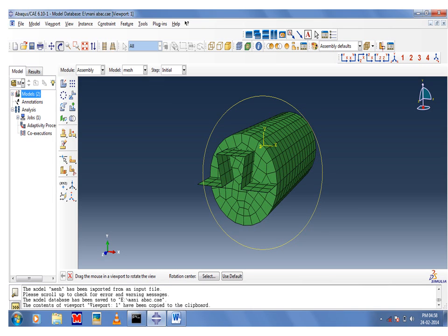The top portion is pulled up from the tuning fork like shape that has been welded on the CF sheet top portion. The bottom portion is pulled down by using a tuning fork like shape reinforcement. The reinforcement was inserted by using a lock fixing chemical to create a higher bond strength while pulling out the concrete. It should not break up on that particular position.